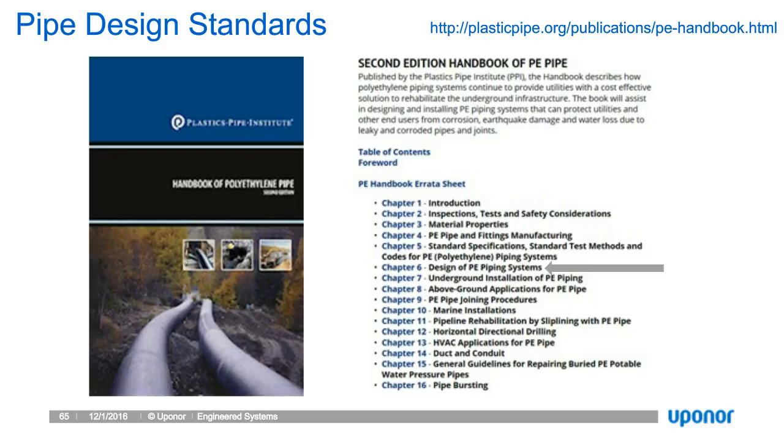design for both structural profile wall, F894 pipe, and solid wall pipe. You can visit PPI's website, and they have an excellent resource there, and particularly Chapter 6 of PPI governs this. And this applies to horizontal pipe configurations.